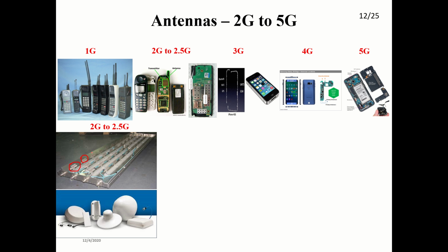That's why they used dipoles, and this is used for 900 and 800 megahertz. One array of dipoles is used for 800, one array of dipoles is used for 900. You can also see the panel antennas you might have seen in buildings, like in-building solutions in shopping malls, theaters and other places.